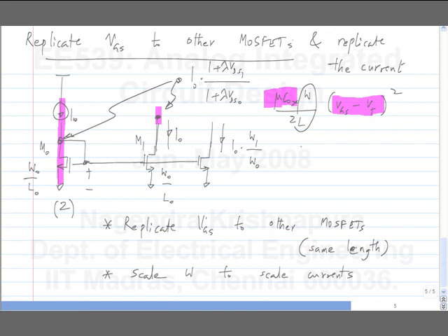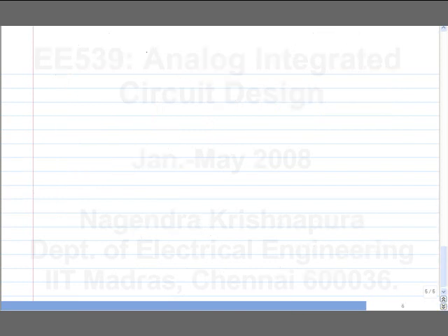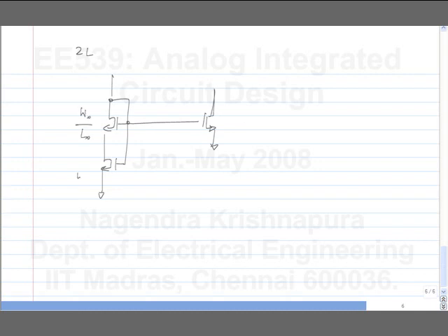Yeah. And then we again have a transistor. We take this gate connection and then have a single transistor. What's the question? Basically, one transistor is W by 2L, but the other one is W by L. So the question is this: instead of making a single transistor of length 2L, you connect two transistors in series, and then you have one transistor on the other side. Let's say all of them have the same W. The question is whether the current here will be double the current here. Again, it's not true.